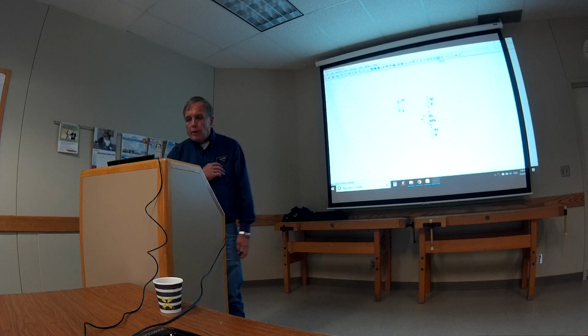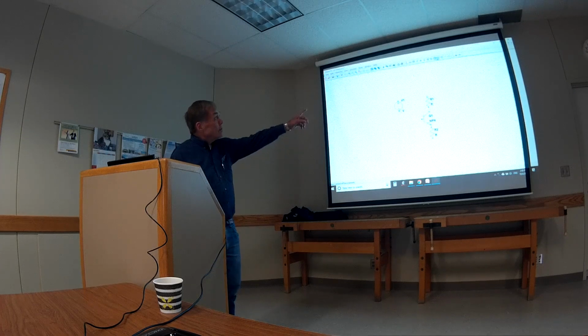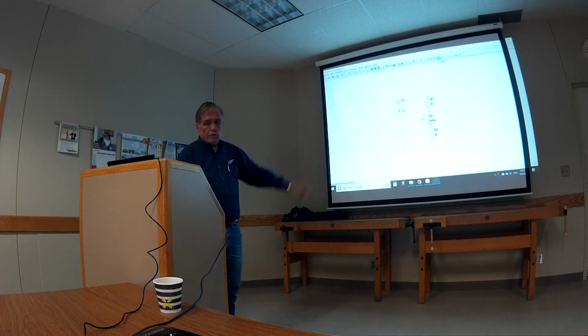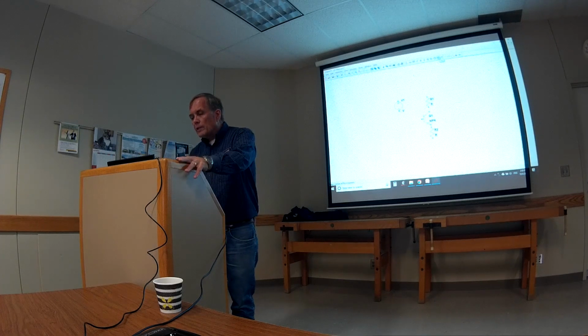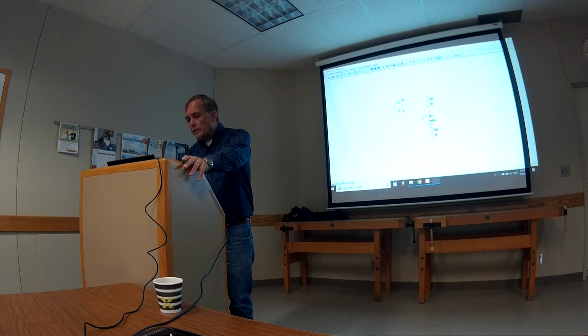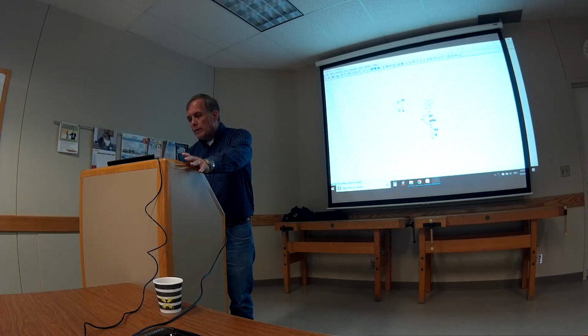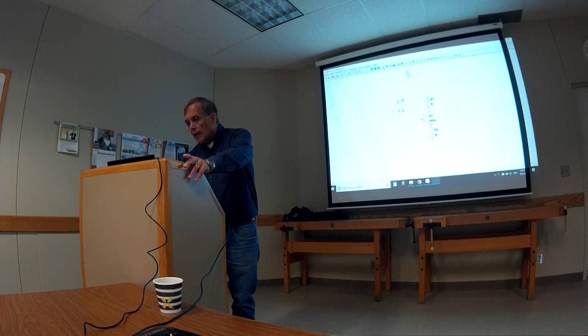Oh, there are two other important things. You see up here where the cursor is? You see the little two hands? One of them is to move and one of them is to drag. So if I want to drag a resistor, you click on that hand, and you click on the body of the resistor, and you can drag it around. You can't do that unless you have the drag tool highlighted. This will keep the wires connected, by the way. I haven't done that yet, but it'll keep the wires connected.